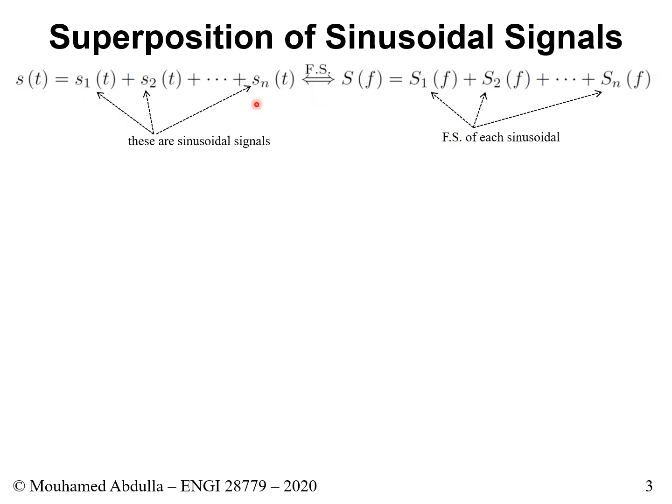And because they are added here, we could also add them in the frequency domain. Now, why is this possible? This comes under the property of linearity. In Fourier series, there are a bunch of properties, and one key property is linearity. So if you add different items in the time domain, you would basically have the same thing: the addition of the frequency response of each of the signals.